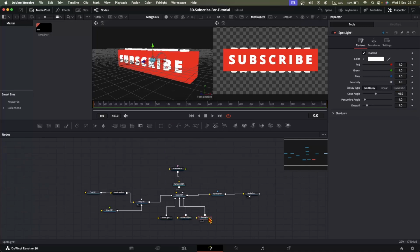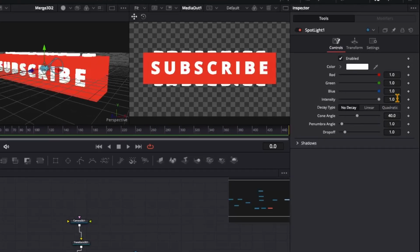and switch to the spotlight. The intensity will be 0.87. Change the penumbra angle to 8.66 and the drop off to 2.88.